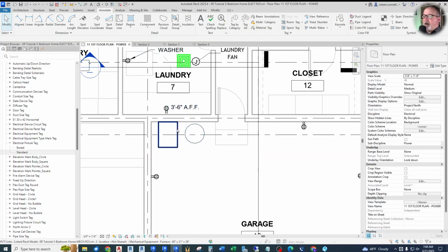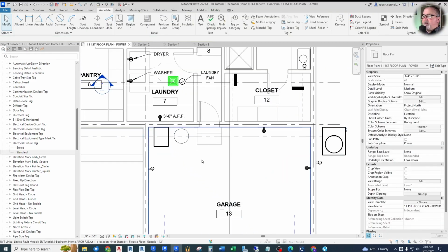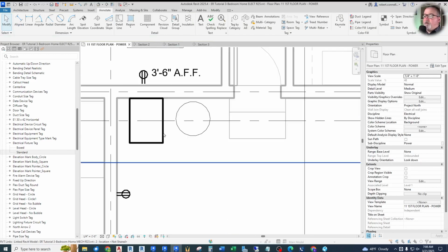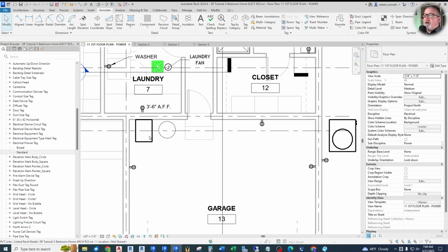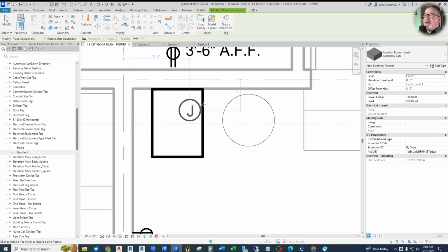Let's tab over this a couple times. And that's a furnace. And we're going to say in this project that we're going all electric furnace. So it will be, let's say it's something like a 20 kilowatt connection. We're going to use our junction box again. Now we don't need the one up at 8 feet, but we can lower it, create similar. And we'll say that its connection's back here.